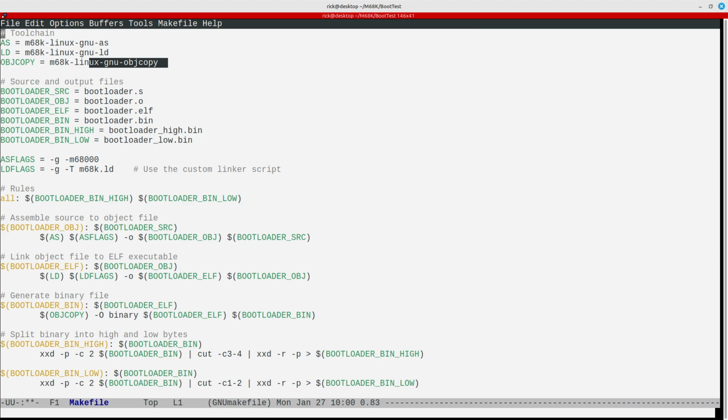So cross compilers let you write software that runs on both hardware and emulators, and that's important because for me, I was using this with the QEMU emulator to try and test the memory, the RAM and the ROM, before I started using the actual hardware. And that's really helpful for debugging purposes, because I can't actually get onto the hardware and do any debugging. Part of my frustration at the moment is I don't have enough debugging information that I can get, because I'm heavily reliant on the logic analyzer and a logic probe, which really isn't telling me a whole lot much of the time.